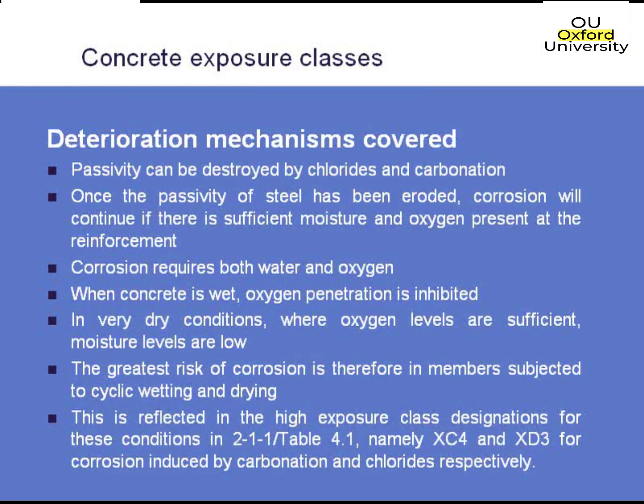If you bury a piece of concrete and it's just wet all the time, yes, it does have access to the water all the time, but there's no air, and therefore the corrosion process is a lot slower. And vice versa, if you've got a piece of concrete sitting in air but never getting wet, it doesn't have the access to the water. So that's why just the cyclic wetting and drying is the absolute worst you can get. And that's also why the XD3 and XC4 have the highest requirements for your cover. It's just to deal with that cyclic wetting and drying process.